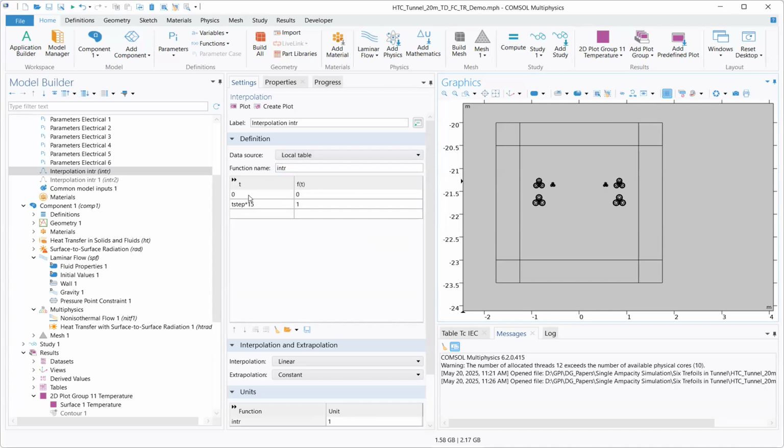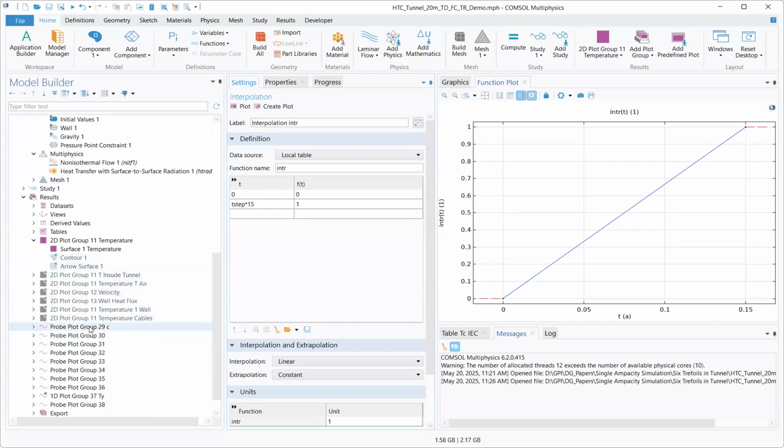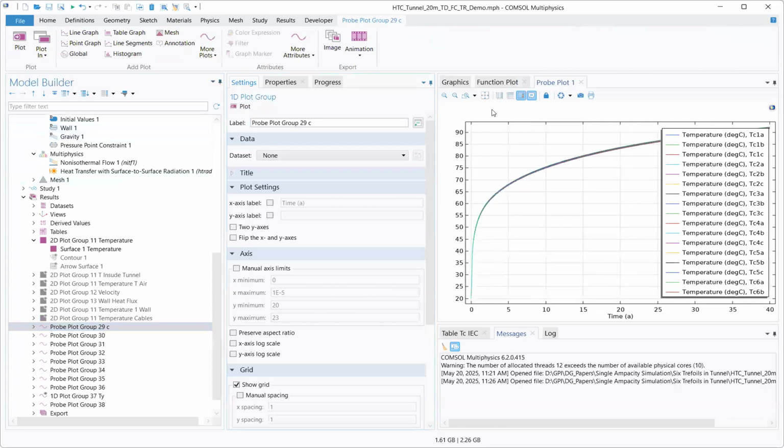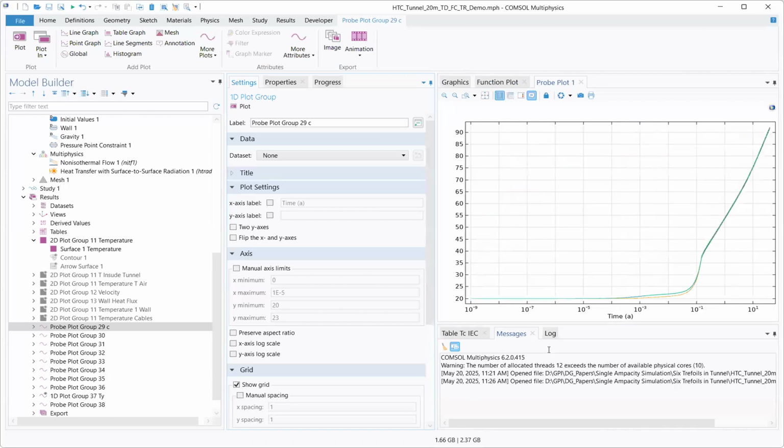It looks like this. The initial value of the heat source is 0, right? So just consider the initial temperature and then reach the full load after 15 time steps. After 15 time steps, the heat source is ramping slowly, and once 15 time steps is reached, the full load is applied. Is it a transient simulation? This is a transient simulation, yes.